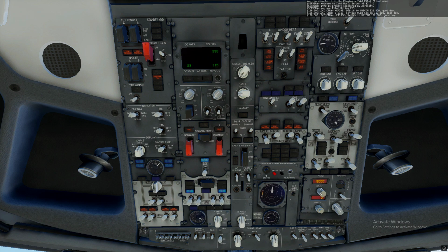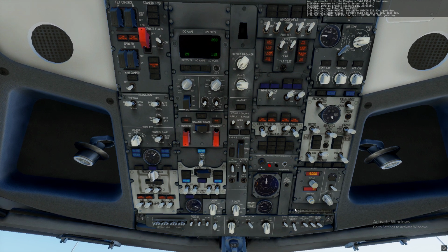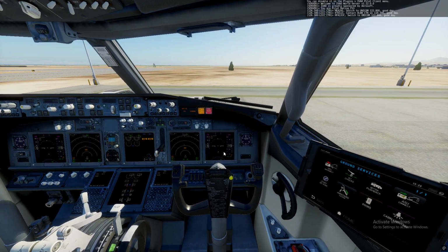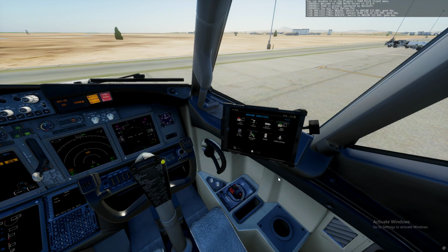Our flight level, as we see in our flight plan, is going to be 150, so we are going to change this to 150. Landing altitude, or the elevation of the runway that we are going to depart or land at. Usually it's the landing. We don't really need it much in the takeoff. In Beirut it's nearly 0, so we keep it at 0, the runway elevation, and this light set to steady. Overhead panel for now can be considered as configured, and I will carry on with other things.